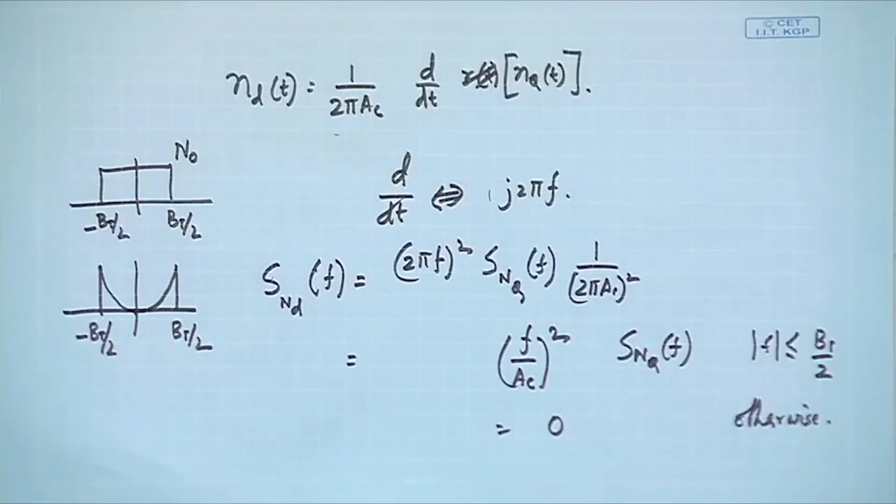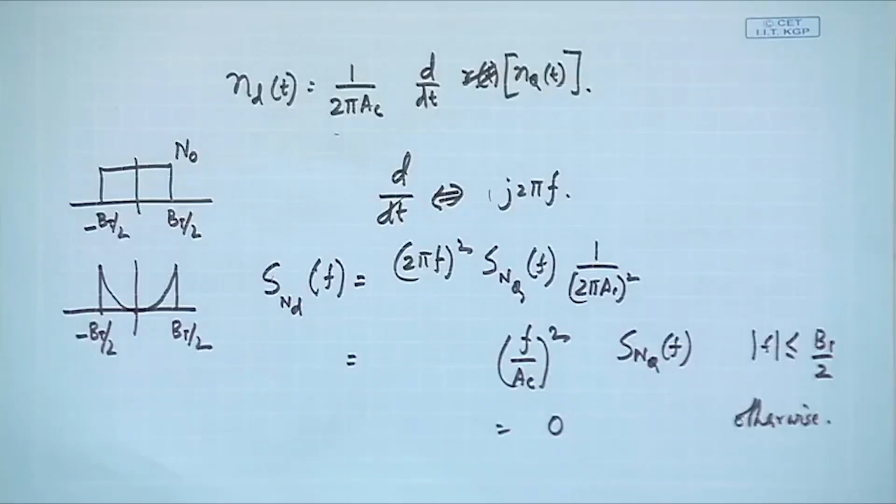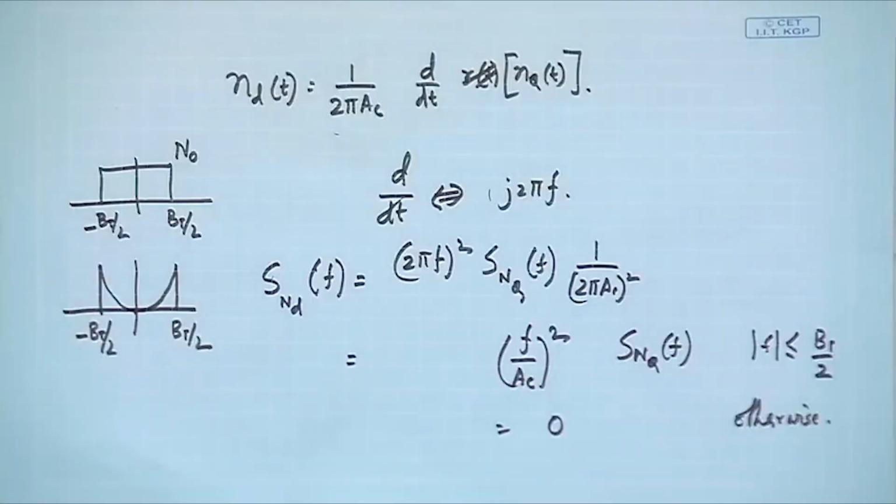If you think a little bit carefully, we have already proven that interference effect. If you take all this noise as if small, at a particular small band, small amplitude of interferers, what does FM do? It captures it, right, and closer to the FM carrier it captures it more, that means it suppresses it. Same performance is happening over here. As you can see, closer to the central frequency, it is actually suppressing those noise, and as you go away from the central frequency, it gets